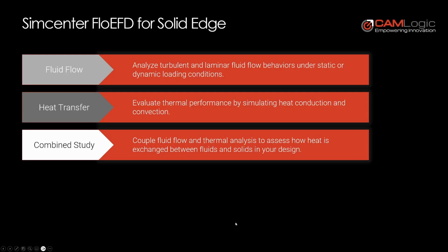And then next is Designcenter Flow EFD for Solid Edge. So again, this is still integrated within Solid Edge. It is computational fluid dynamics, and it's using a different solver than the FEA studies. This allows you to do fluid flow, so you can analyze both turbulent and laminar flows under either static or dynamic conditions. So you can do transient studies or studies that have changing conditions.